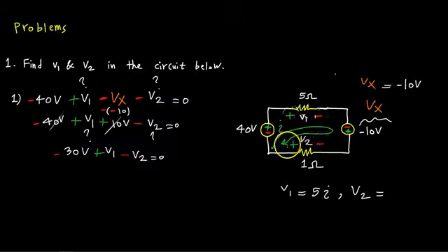But V2, we're going to look at it and we're going to see that the current is going to go against the potential drop here. So it's going to go from minus to plus. So therefore, according to passive sign convention, it's going to have a negative value. So it's going to be a negative I times the 1 ohms. I'm just going to write it this time because it's early on in the lecture series. So it's going to be 1 ohm, to keep the units in voltage. So we know the relationship between V1 and the current and V2 and the current.